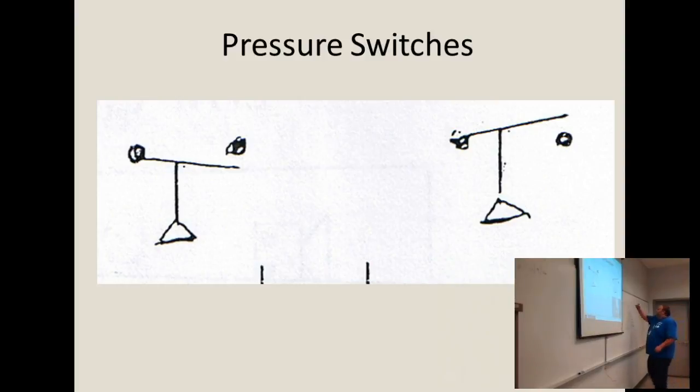So, what kind of pressure switch is that? A low, right? Pressure drops, what happens? Opens up, protect my equipment.